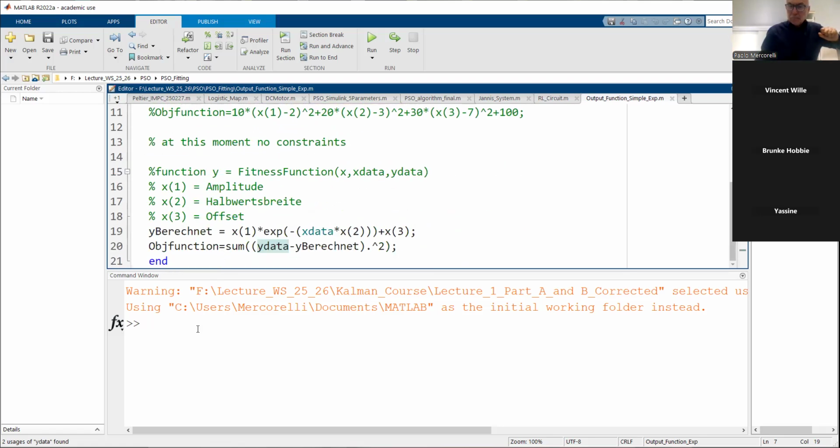Now, the objective function we can see here is the least square. You remember I told you last time. This means the sum of the squared errors. Error of what? The error between the corresponding measured element in terms of roughness using the glossmeter, and the corresponding, again, this is a very important word, the corresponding element of the regressor.